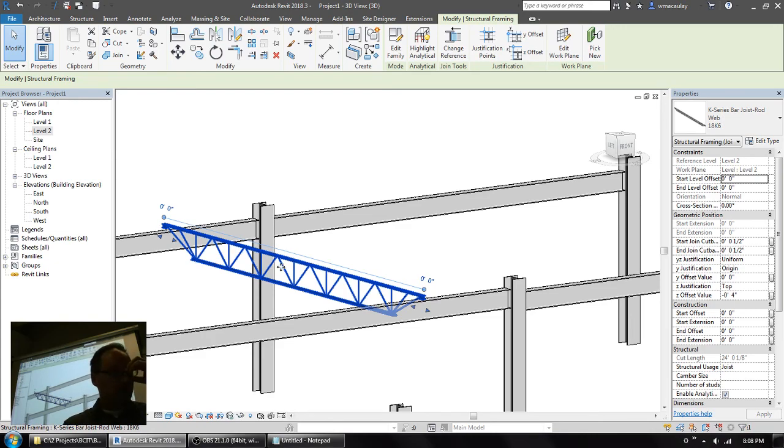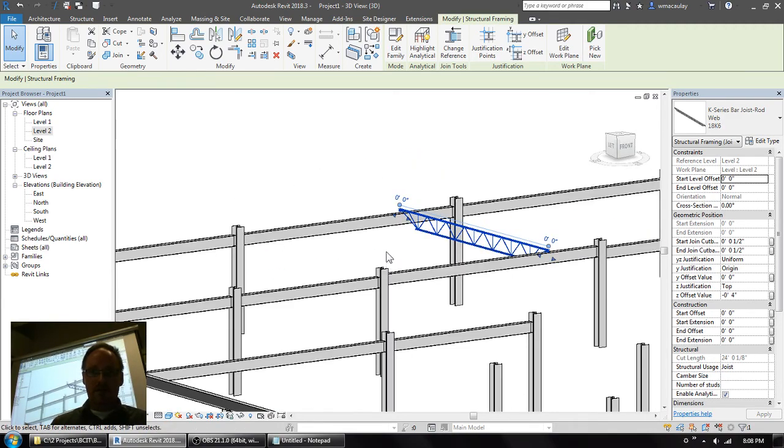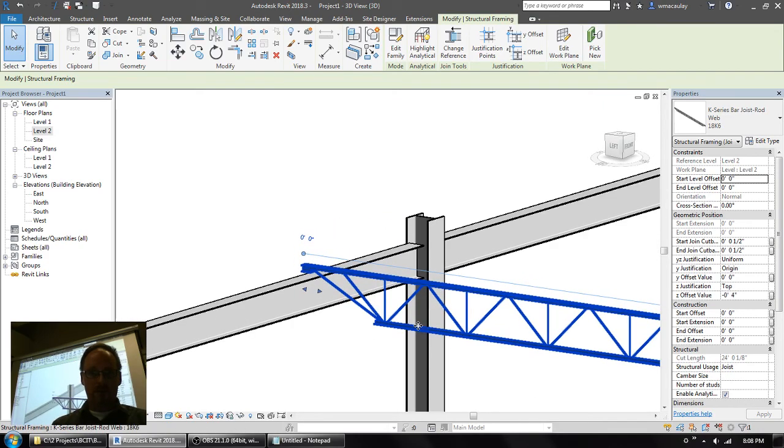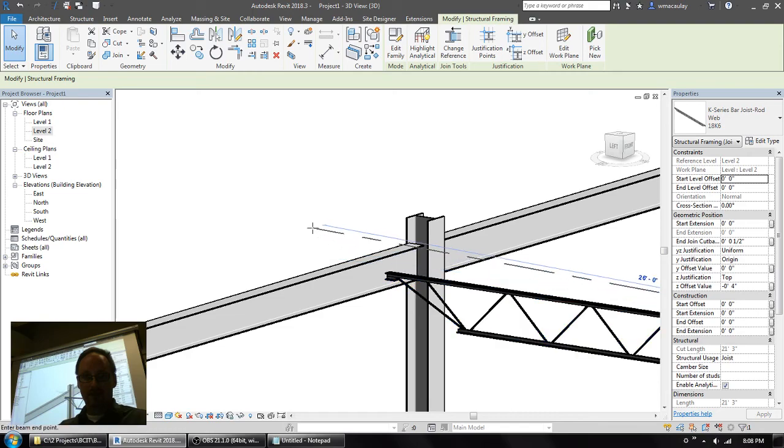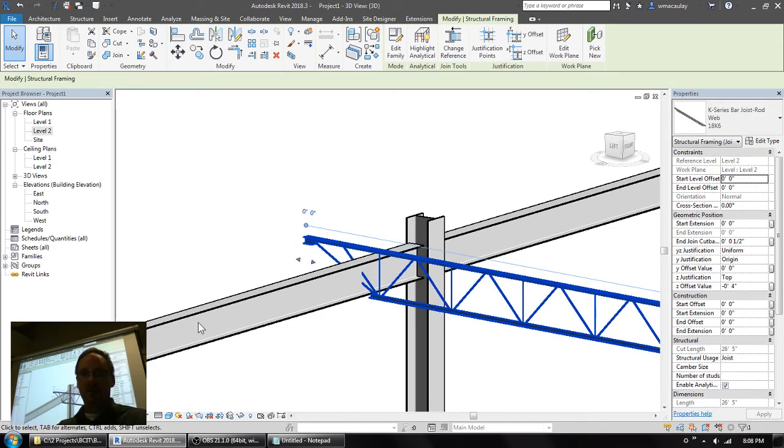Now, top of page 3, beam end handles and shape handles. Some structural objects have 2 sets of controls. The dot handle is called the beam handle. That is the one that actually changes the length of the beam. And there it is there. The angular controls change the non-structural length of the beam. And in the case of an open web steel joist, typically you will drag them outwards to create a longer